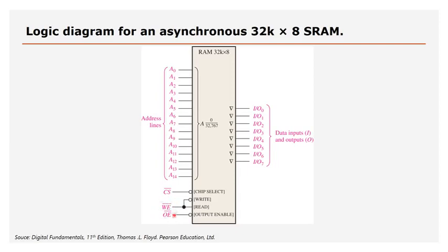So that determines actually the input or output of data flow into this device. If it's a write enable, data will be written into the device. If it's an output enable, data will be read from the device out on the data bus. And again, the address lines determine which position we are going to access inside this device.